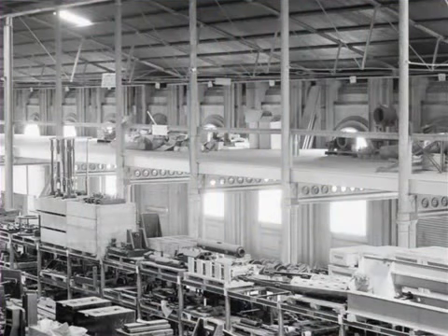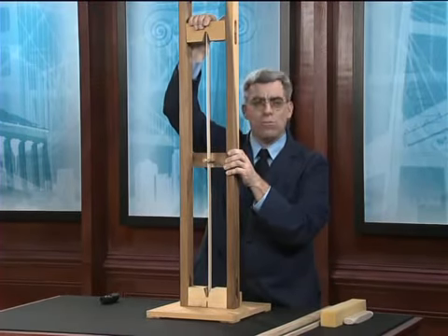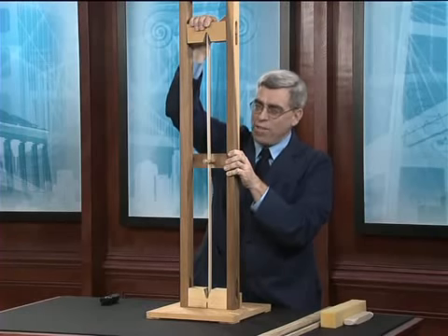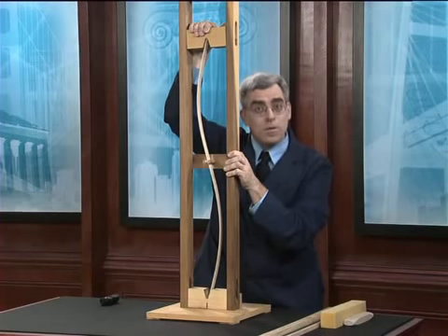But the Watervliet Arsenal building has this second floor gallery located right here. And if you look closely, you'll see that the column itself is physically attached to that second floor gallery, which then has the effect of adding a point of lateral bracing to the column. As a result, if we really loaded this column to failure, we would see that it buckles not in a single curve, but rather in a double curve or S shape like this.